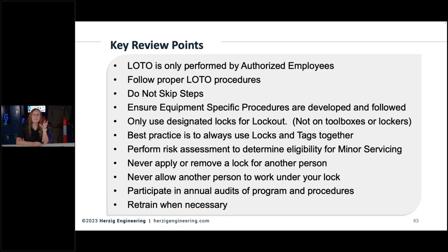And they're like, well, yeah, we had to refeed this, and now this valve broke, so we put in a splice or whatever. All kinds of things get changed over the course of a year or two. And I'm like, okay, so has that procedure been updated? Oh, probably not. Have you told anyone that there's been a change? Oh, no, I didn't think to. So go review them, make sure that they're up to date and able to be followed, because maybe that one authorized employee knows what they're doing and is solid, but what if they call in sick and someone else needs to work on it? What are you going to do? How are they going to be able to apply those LOTO procedures?